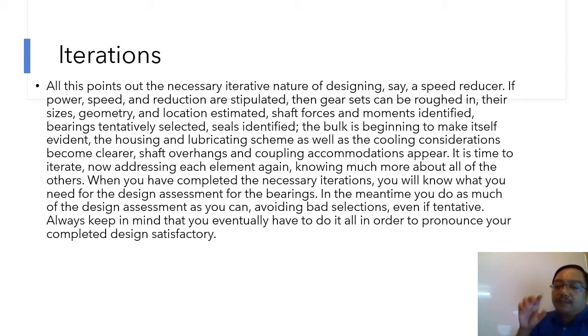Let's say you have the shaft of this size, and then you are going to put the bearing. You have to choose the bearing, the C10, the catalog rating for the bearing, and the dimension of the bearing suitable for you. In the end, there are many things you have to take into consideration. If you calculate and you're not satisfied, you do the calculation again and again until you are satisfied. Then in the end you select the better parts and tools for your design.